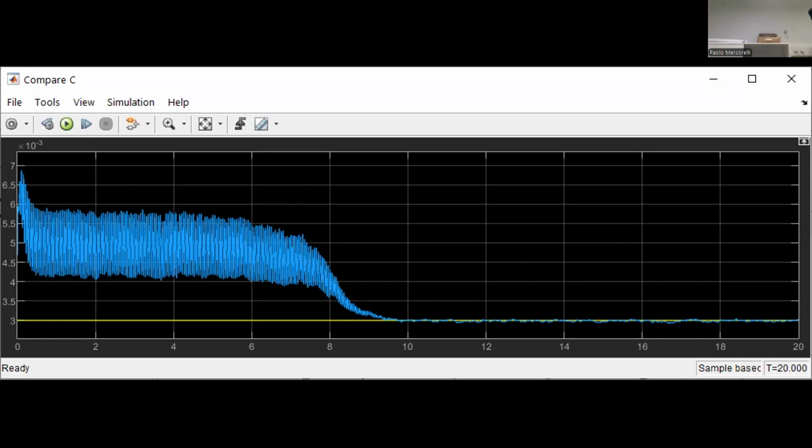That physically makes no sense. You remember, in the extended Kalman filter there is no guarantee of optimality. I will show you this again in the future. No guarantee of convergence, because it's an approximation of the problem, something like a convexification of a problem which is not convex. But if not convex, it could also diverge. Putting something not physical, we say to the Kalman filter, please pay attention, R is negative, no sense. I show you what happens.